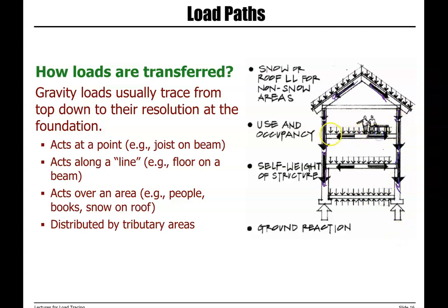Also, when we get to the flooring system, we have to add the live load and dead load of our flooring system. And then we add everything together to find the total ground reaction. So the path is from top to down until we get to the ground reaction.